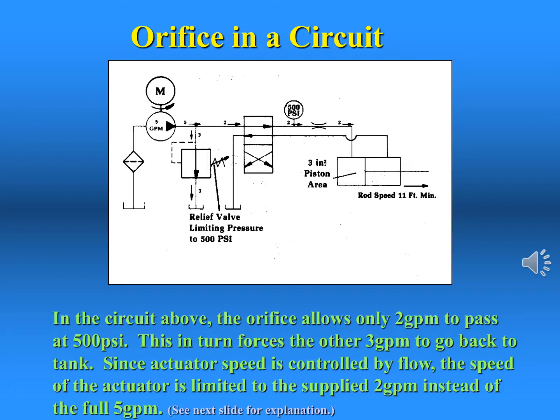The measurement is a combination of speed in seconds or minutes and distance, which could be in feet, inches, meters, and centimeters. In this case, the measurement is the speed of the cylinder rod in feet per minute. The majority of my demonstration calculations, however, will be in units of inches per minute. Note that the relief valve here is shown as activated. This is for illustrative purposes only, because this is never done in the case of an industrial schematic diagram.